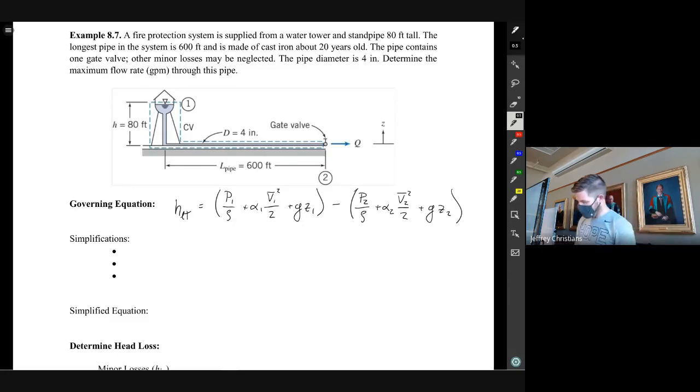Okay. Then you want to go through and actually look at your specific problem and say, which types of mechanical energy do we have at which locations? So we can simplify this a little bit. Our first simplification: our two control surfaces are the top surface, that's 1, and the outlet, that's 2. We're shooting to atmospheric pressure, so at the outlet, that's going to be atmospheric pressure.